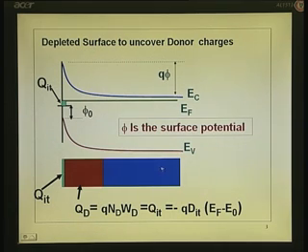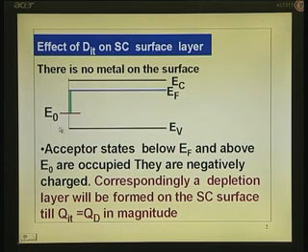region. Notice one thing, I will go back to the original diagram, here the entire charge was here, but as it starts bending down, this point comes down, along with that the Fermi level in that portion comes down. So, as the Fermi level comes down, the occupancy here goes down, because levels below EF and E naught are occupied. When the depletion starts building, the Fermi level comes down and fewer charges are occupied. So, this process takes place till there is equilibrium between the charge in the interface and the depletion layer.